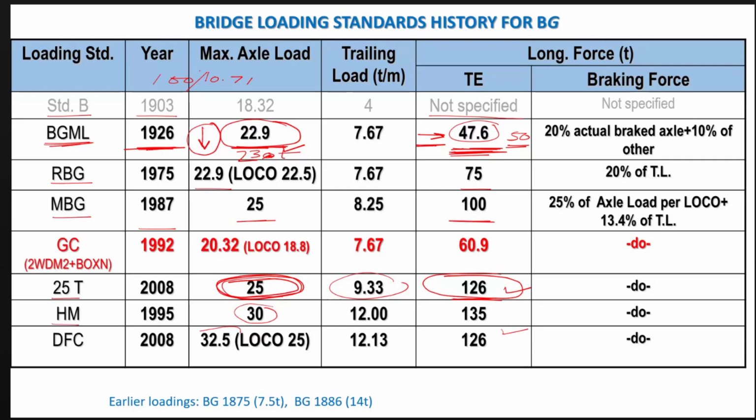Welcome. Sir, for a few bridges RDSO has not given any drawings, and we are not able to get any standard. We have to really design. We are replacing existing steel girders with PSC, and for skew there is no standard design available in RDSO, sir. So we have to design by ourselves, and we cannot go for RCC beyond 3.5 meters. Previously we used to design RCC slabs even for 12 meters in our railways, but now CRS objects, asking why we are doing it for more than 3.5 meters. So essentially we have to go for outside design only, and all of them become non-standard.